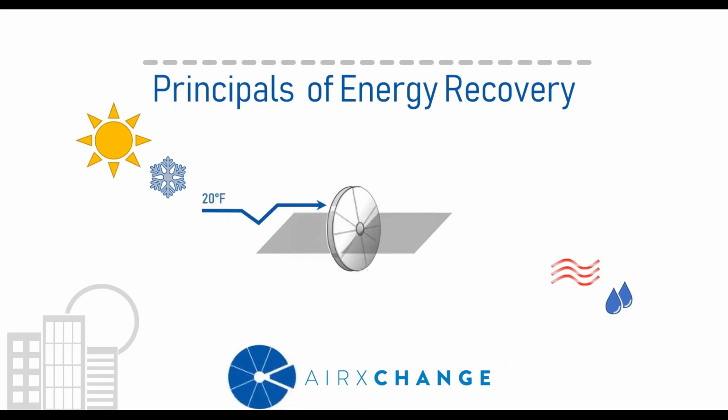Now, pulling that wheel out of the system, let's take a closer look. Here you have outside air coming in at 20 degrees, and you have the exhaust air leaving the building at 75 degrees. A percentage of that heat is going to be used to warm the incoming air to 63 degrees. And since that heat was used up in exchanging it to the ventilation airstream, it means that the leaving exhaust air is going to be a lot cooler.